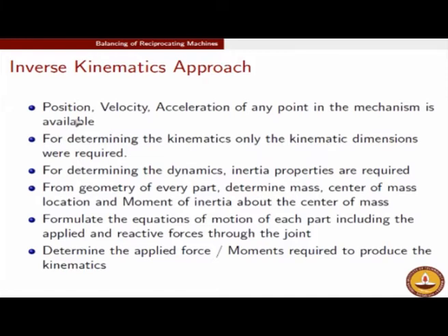To be specific, we will look at the moment that is to be applied at the crank such that we get uniform angular motion of this crank. So, this is the inverse kinematics approach. Please understand this approach is in contrast with the forward dynamic approach.